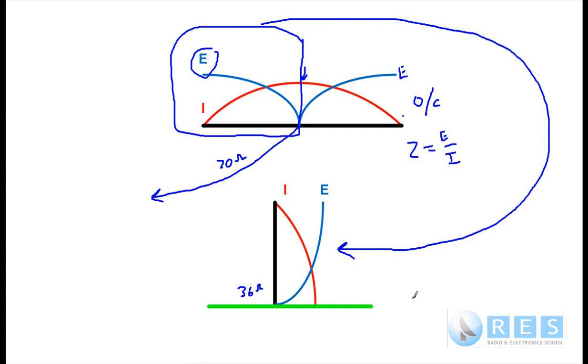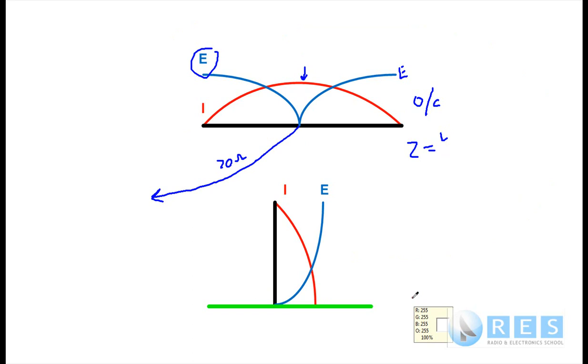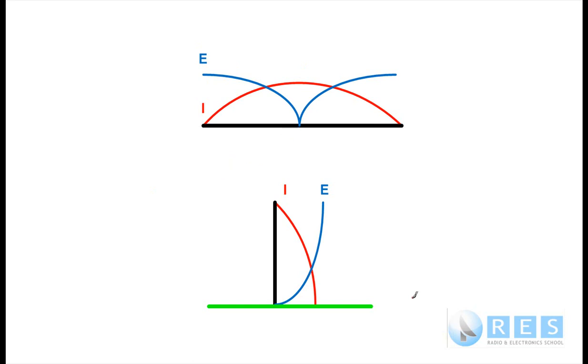And you need to remember, you may have to identify those diagrams. I'll just take all my rubbish off. What you could get in your exam is either one or even both of those diagrams and be asked what it is. And that would be a dipole antenna. Or you could be asked about the current distribution or the voltage distribution of a dipole. And if you remember, high voltage at the ends, low in the middle. Low current at the ends, high current in the middle. And a similar situation for the quarter wave vertical antenna. Be a good idea if you remembered those.